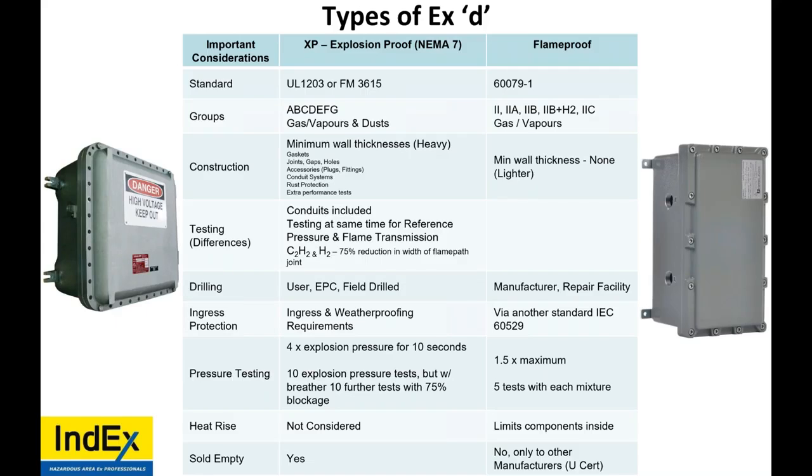Another one that Thorne from Stahl actually gave good input on: explosion proof is only for Division 1. EXD, flameproof, is only for Zone 1. So when people say EXD, this confusion is going to continue because EXD is used for calling explosion proof and flame proof. And some trainers around the world continue to spread this inaccuracy.